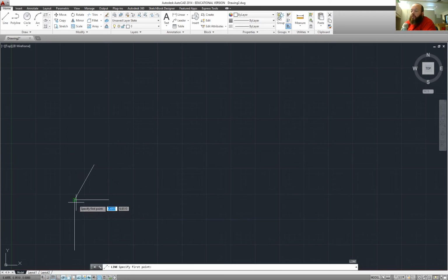Okay, again, we're going to snap to that point there. Click the mouse. We're going to pull the line out a little ways. This line is going to have a length of 3. Now, if we notice here on the angle, let me move the cursor so you can see, the angle is being measured off of the horizontal line there. If we look at our drawing, it's given off of the last line we put in. So we're going to do 60 plus 60. I know you have to do a little math, so we're going to type in 120. We'll hit enter. Hit enter one more time. Now we have the bones of this thing put together.